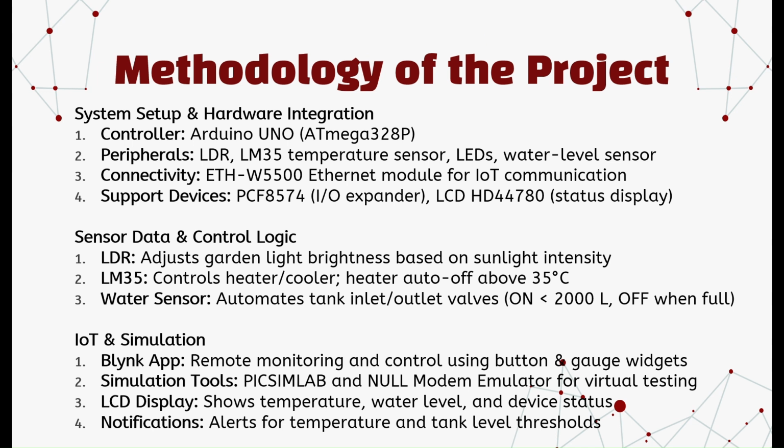Hi all, my name is Rupnath and I am going to talk about the methodology of the project, system setup and hardware integration. We have used Arduino Uno as the controller, and the peripherals are LDR, LM35 temperature sensor, and water level sensors. Connectivity is through the ETH W5500 Ethernet module for IoT communication. Support devices are PCF 8574 as input output expander and LCD HD44780 as status display.